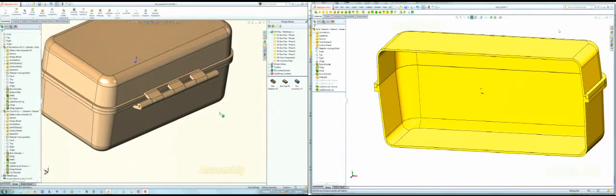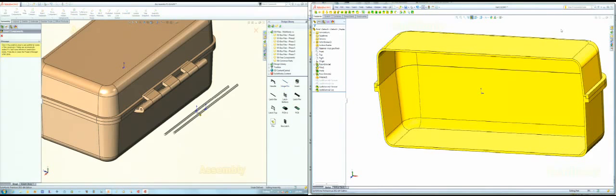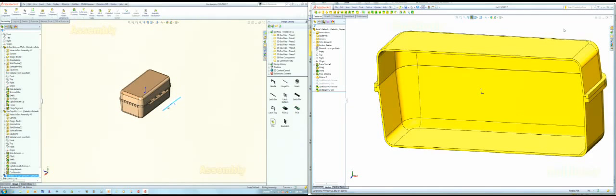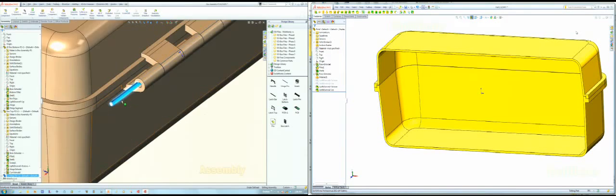What's left? Got to put a pin in it. I'm going to do this a little different than Phil's about to do it. I've already got the part created. I can just drag it over here into the assembly, and then we can just mate this into the hole. Oh, come on. Then move it in close enough. Okay, move. There we go, closer. Okay, grab that, hit the Alt key, drag it in there.